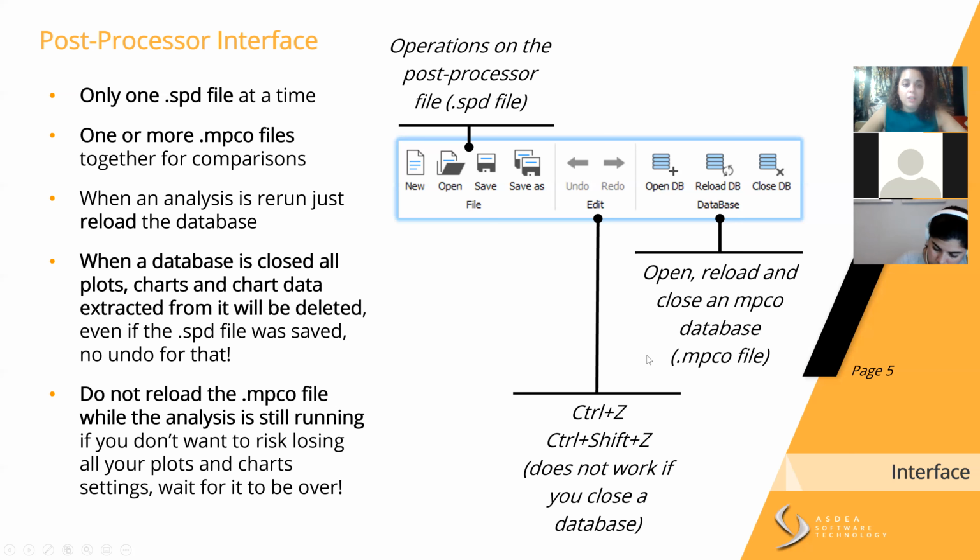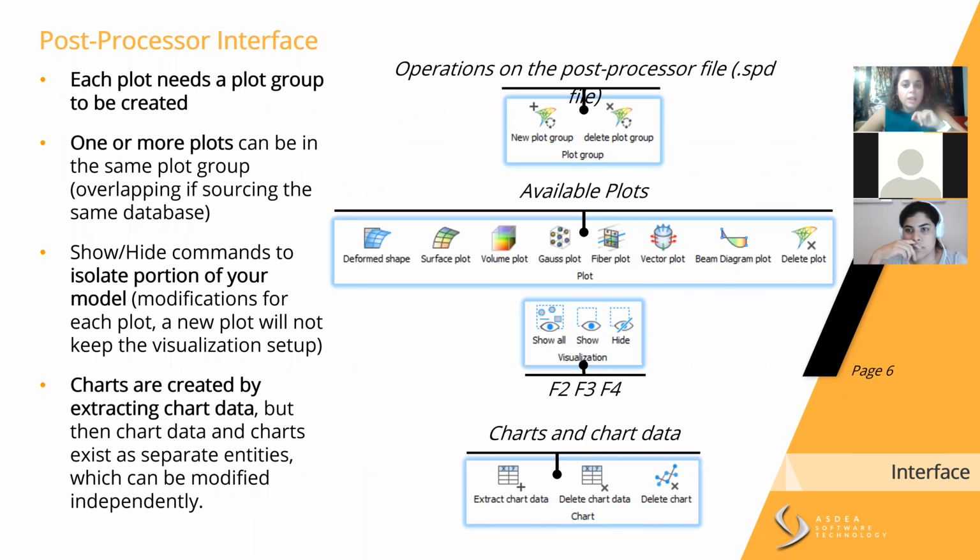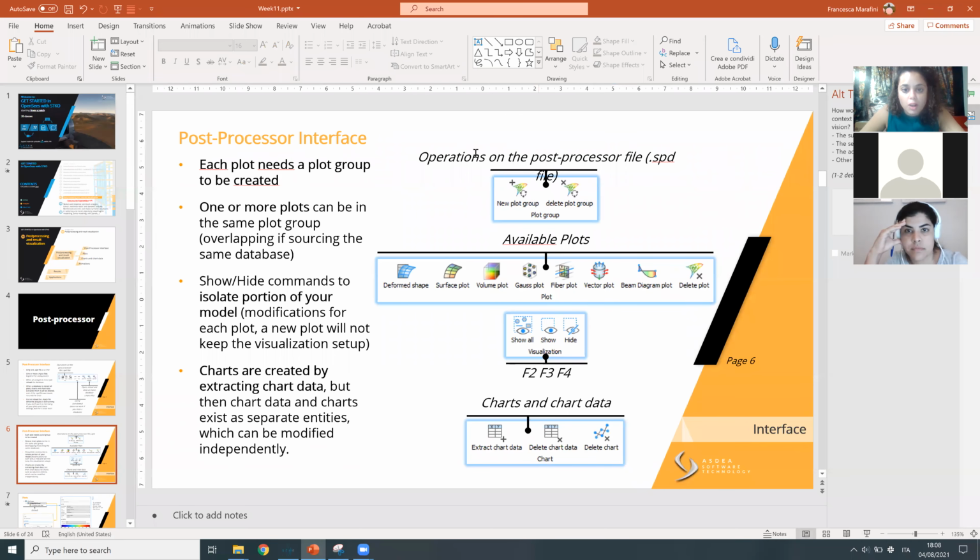You can have only one SPD file at a time, but in the same SPD file, so in the same post-processor interface, you can load more than one database at a time, so that you can make comparisons, for example. When you close it, all the charts, plots and data that you extracted are deleted. So remember, you cannot undo that. And you can open the file as the analysis is running. This I already said. Then we have, sorry, here there's something wrong.